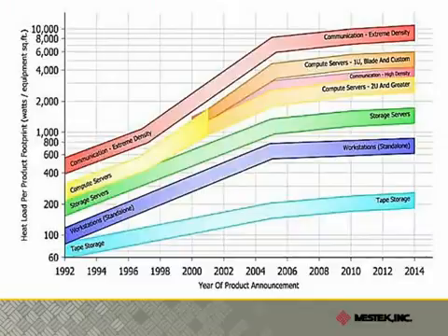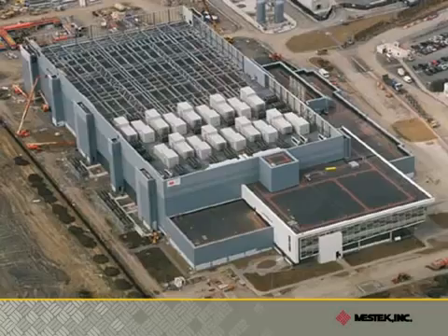And that heat load is growing with the increasing server densities that are necessary to meet the rapidly growing demand for digital information transfer. The numbers on this chart should simply astonish most people who are more familiar with conventional HVAC cooling requirements. While a typical commercial office building might have cooling requirements of 10 or 20 watts per square foot, you can see that some IT applications have cooling requirements approaching 10,000 watts per square foot of equipment. Even if you spread the equipment out over a warehouse-sized space, it is obvious that the cooling load is enormous.